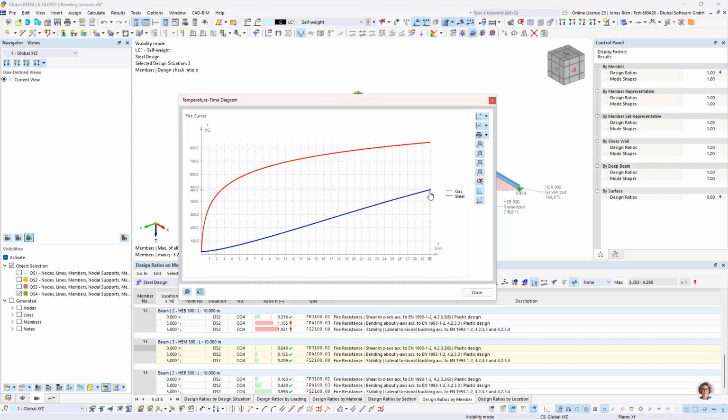And that's mostly because for the whole 30 minutes, we are below a member temperature of 500 degrees Celsius, which means that we, until the end, can benefit from the lower emissivity of the member surface. And then, of course, the benefit is much greater, because it's more or less the integral of the heating over the time.